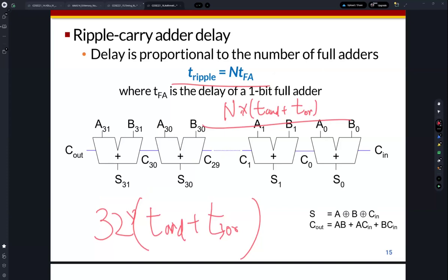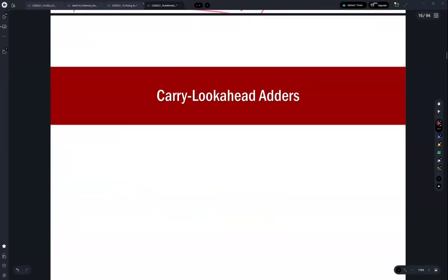Then we need to implement a faster adder. And how? What's the problem? What is the cause of this long delay? It's the slow path of this ripple carry adder. It's carry generation, right? So if we can generate carries more quickly, we can increase the performance. Obviously, right?